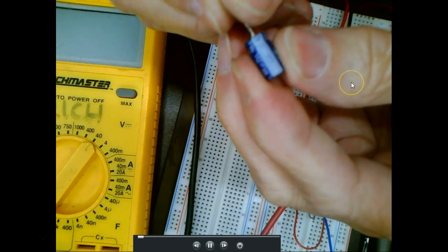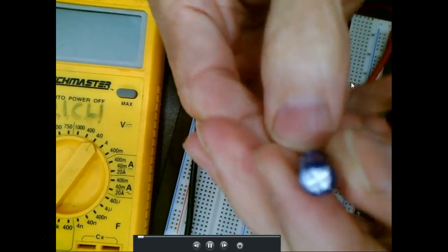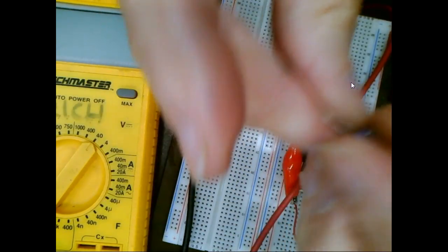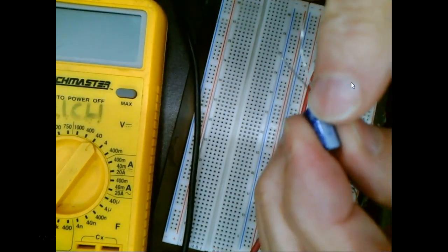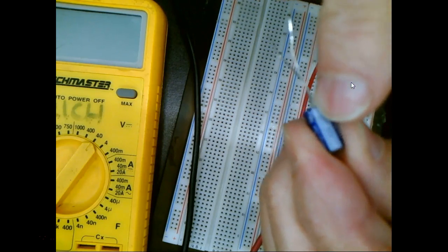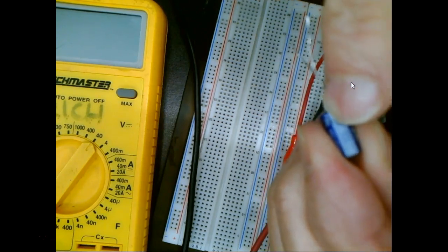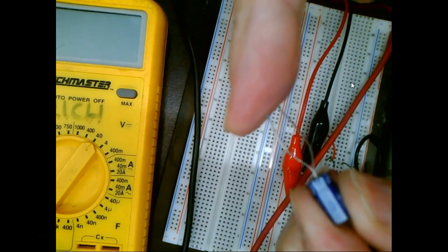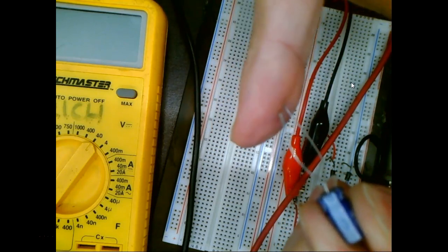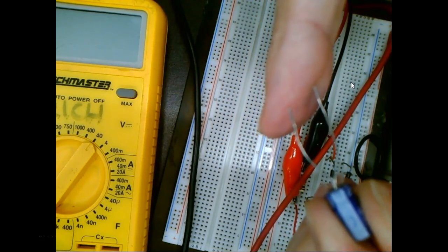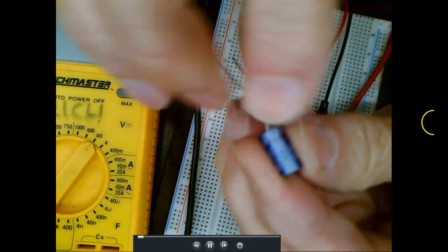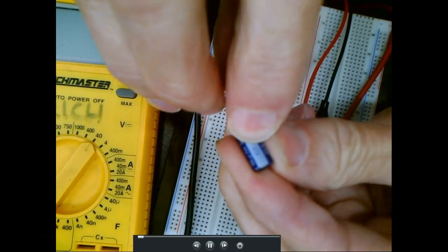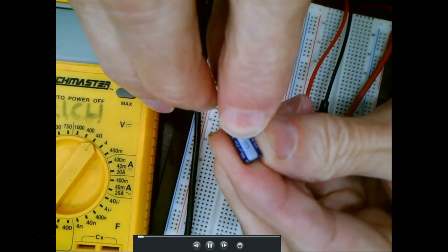This is a polarized capacitor, and this is what we call a radial lead. For some reason, on the radial leads, they identify the negative side. Y'all see this big white stripe with all these negatives coming down? That means this is the negative side, and this is the positive side. Are you okay? Yeah, you can't see the little minus sign, but that's the little minus. Yeah, y'all can. That's the little minus sign right there.